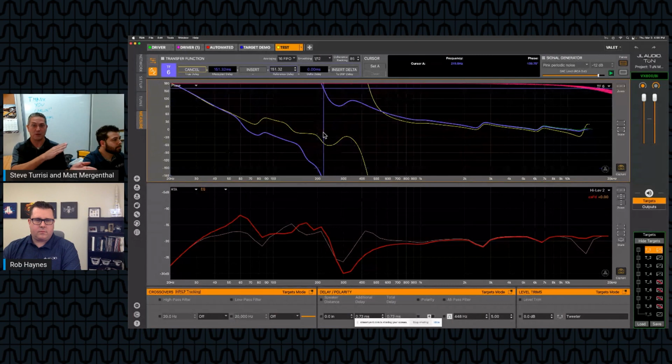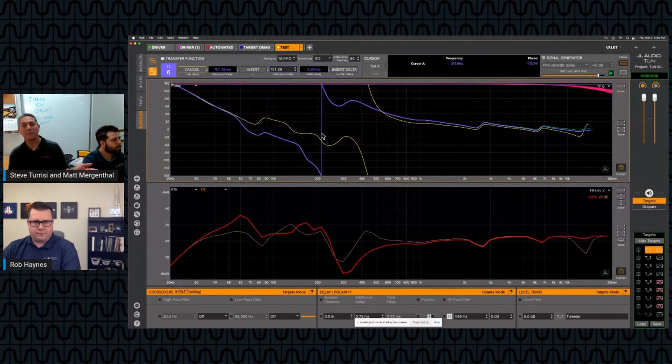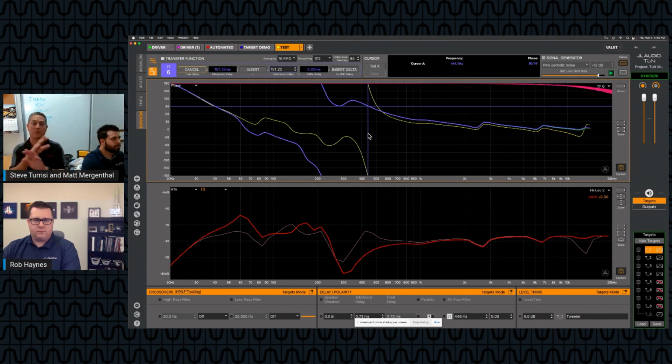So you change the all-pass to the other frequency. Now you still have the other problem. So which one do you put on which channel? This allows you to see exactly which one to put on which channel. You see, if you put the screen back up, the wrap that's on the purple, you put that all-pass on the yellow. And the one that's on the yellow, you put that all-pass on the purple. So you're counteracting what's happening on both channels.